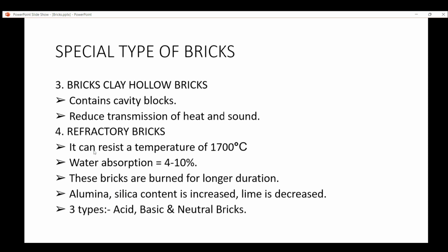Refractory bricks can resist temperatures of 1700 degrees centigrade. Water absorption is 4 to 10%. These bricks are burned for a longer duration. Alumina and silica content is increased, and lime is decreased. To produce these bricks, we decrease the proportion of lime and increase alumina and silica. Refractory bricks are divided into 3 types: acid bricks, basic bricks and neutral bricks.